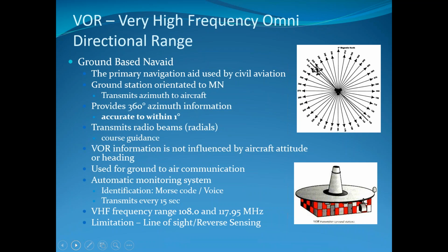So the METAR is magnetic, right? A METAR is you read it, so it's in true. Anything you read is true. The only difference, though, is that, like I said, if you're using the software at work to do flight planning, and you pick a runway that they're going to land on, that software will automatically do it. So you're not having to do this for every flight. It's really very limited that you would ever be calculating magnetic variances.